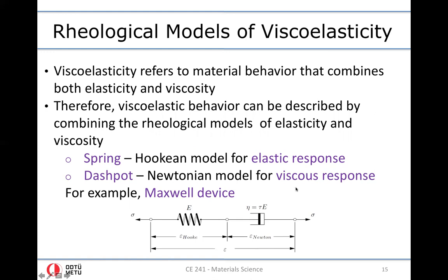And the dashpot is the model in which we have dissipation, not the energy storage, but the dissipation. All right. So dissipation can be considered in the dashpot that is actually nothing but the piston that is filled with a liquid, viscous liquid, and the friction between the fluid that is flowing between the piston and the cylinder dissipates the energy that you externally supply.